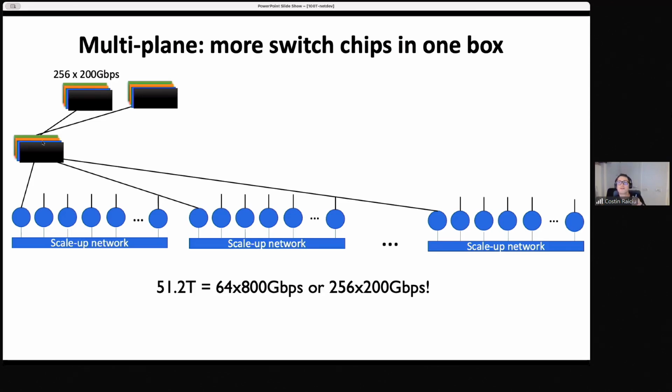So on a single optic fiber, you can basically carry multiple lambdas, and each of these lambdas will be 200 gig. So you have a single transceiver here, single transceiver here. Still, you pay for a single wire, but within the switch, when you go from optics to electrics, you'll basically have 4 copper backplanes going to the different chips, right? So now, logically, you've got 4 different networks that are completely independent, and these are called planes.